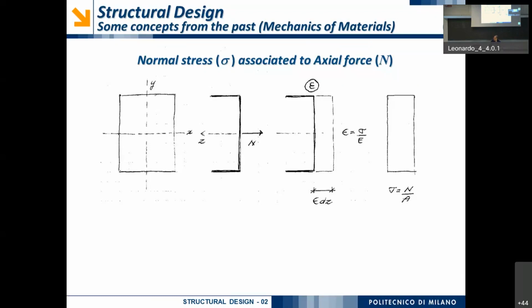So, the strain, the local deformation, is the variation of length divided by the original length. So it's a pure number. I do not measure it in meter. Generally, I measure it as a pure number, and in fact, in the textbook, you can find the strain expressed in, for example, percent or points per thousand. Okay?